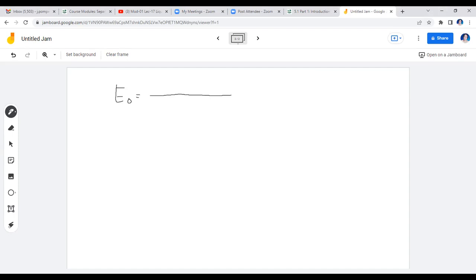The formula that you took a screenshot of for the tray efficiency is 0.352, T raised to 9. And you have the sigma. You have the diameter of the tray hole. And you have here the ratio of the dispersed and the continuous phase flow rates. Actually, class, this could be flow rates, this could be velocities, either of the two will do. Okay, so raised to 0.42.